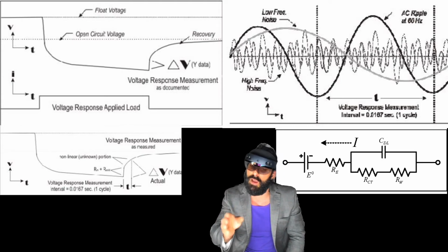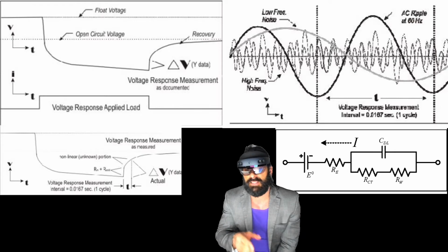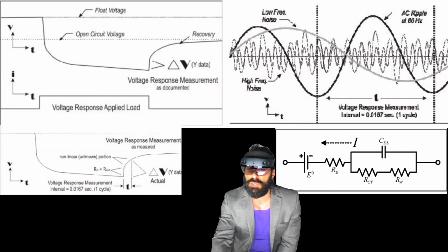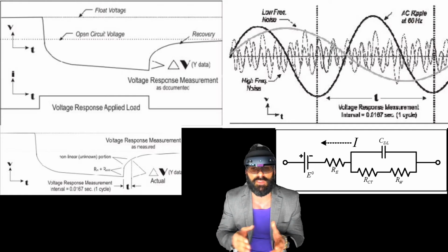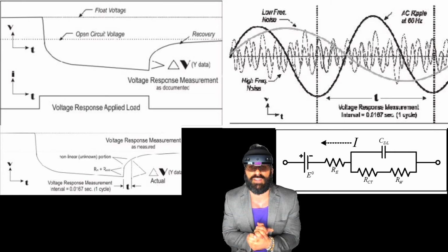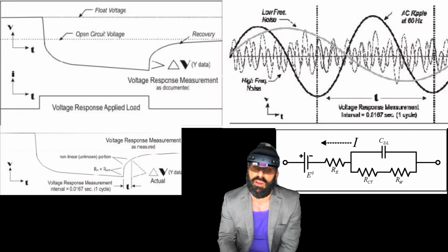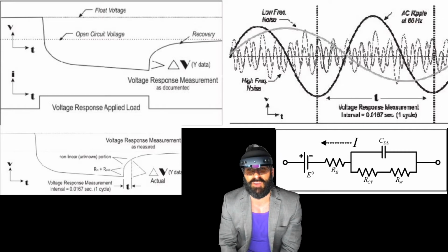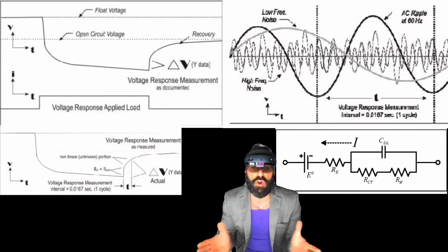This is why I do not see single frequency testing methodologies or products as advantageous, and I'm a huge proponent of using multiple frequency electrochemical impedance spectroscopy. What this is doing, and I think there's only one company called Cadex that actually uses this in the market. I'm surprised I don't see it more in the data center industry, especially with lithium coming into all the different facilities now. These types of instruments inject from 8 to 30 different excitation frequencies at various frequencies.